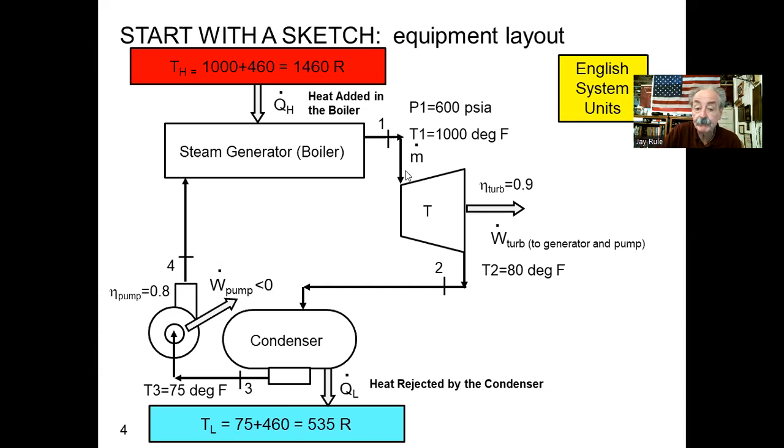These arrows are basically going to be pipes, okay? Inlet to the turbine. I've shown this little trapezoid as a turbine. The steam is expanding as it's producing power. That's why I've shown it as this trapezoid. Look at this, I've shown a block arrow showing W dot of the turbine, that's the turbine's output power. I've labeled the turbine efficiency, 90%.